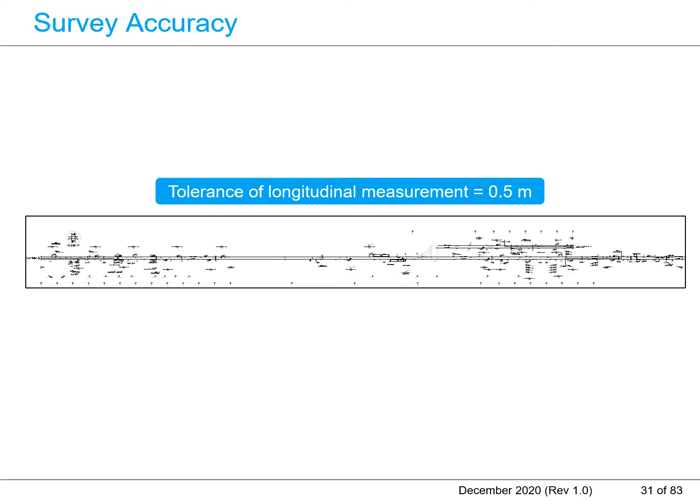The proposed location of the trackside entities will initially be based on the longitudinal distance information derived from the signaling plan record. The ETCS operation is sensitive to the balise group location data. Therefore, higher accuracy of survey is essential for the ETCS Level 2 project. The maximum tolerance for the longitudinal measurement along the track from the survey is 0.5 meters.